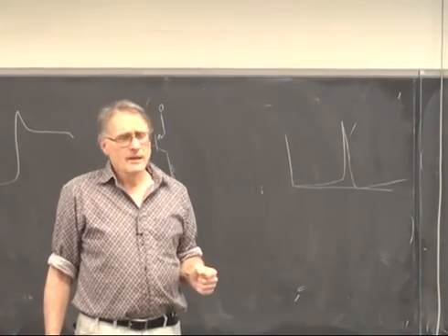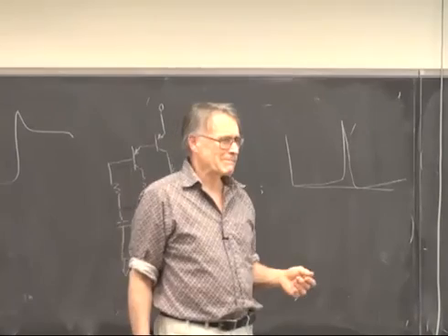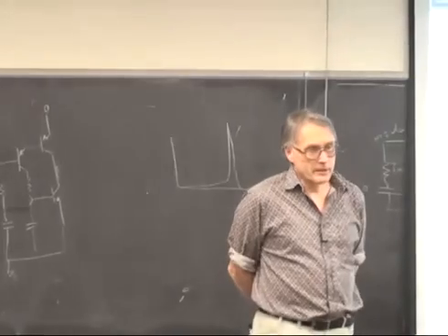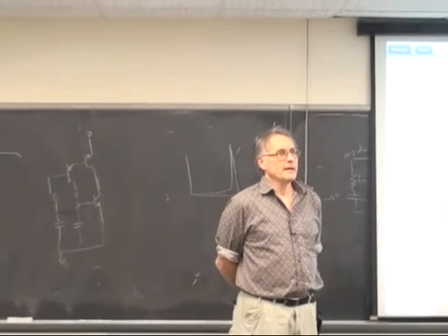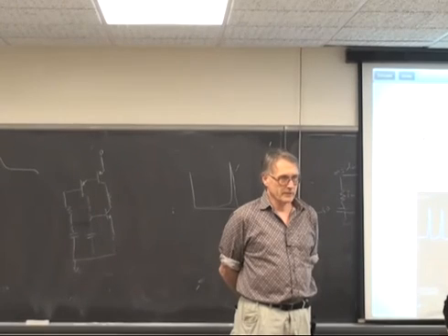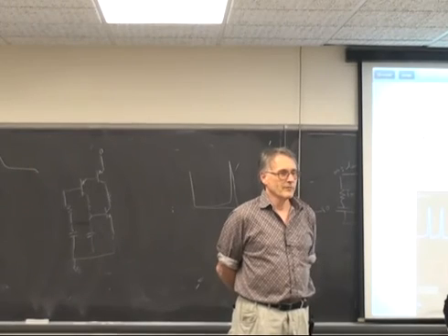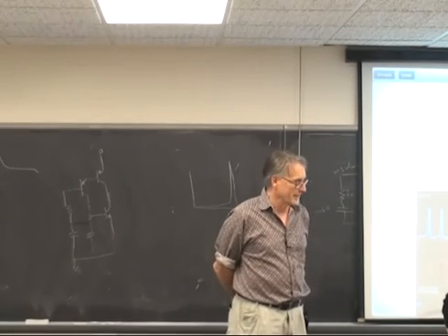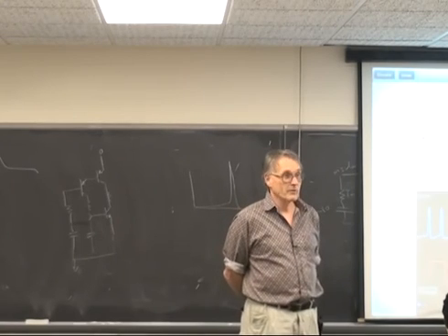Any questions on this? Just out of curiosity, how does SPICE solve these circuits? Okay. If it's a linear circuit, it's easy. You can write Kirchhoff's laws for all of the nodes if it's a linear circuit, and what you come up with is a matrix of derivatives and first order relationships. And it can be inverted. Once you've inverted, you've solved it.